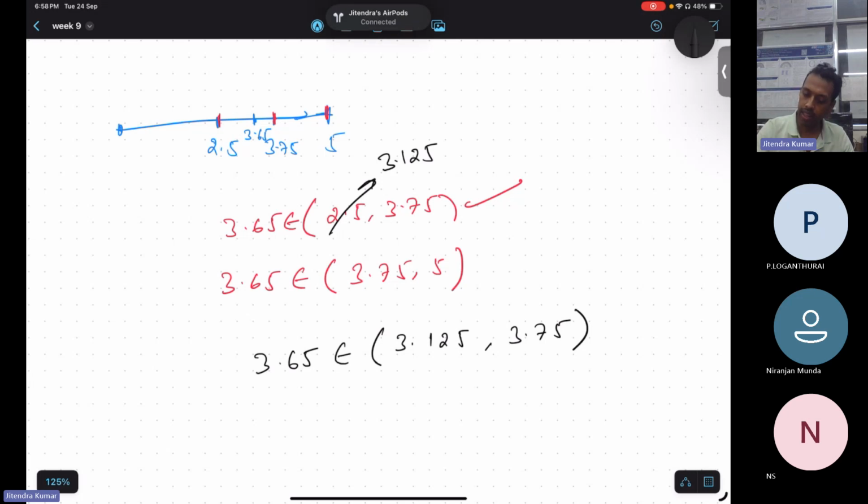Fine, so further it will divide, it will again perform the binary algorithm, and again it will find the midway. It is just like the binary algorithm, the first one you studied in numerical methods. It keeps halving until it finds the value. So basically it will reduce all the efforts of calculating at each clock pulse with increment in each resolution. So instead of 2 raised to power n, it now has to perform n times only. Are you getting the idea behind it?